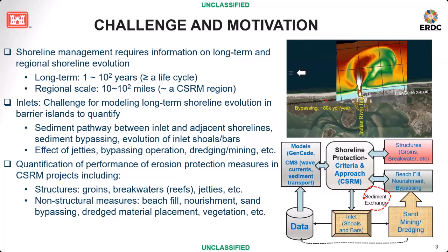Traditionally we use breakwaters, groins, jetties, and seawalls to limit the change of shoreline, reduce longshore sediment transport, and stabilize shoreline variation. Non-structural measures are very popular, such as beach fill nourishment. We may have nourishment before and after a storm, so you can call it pre-storm nourishment and post-storm nourishment.